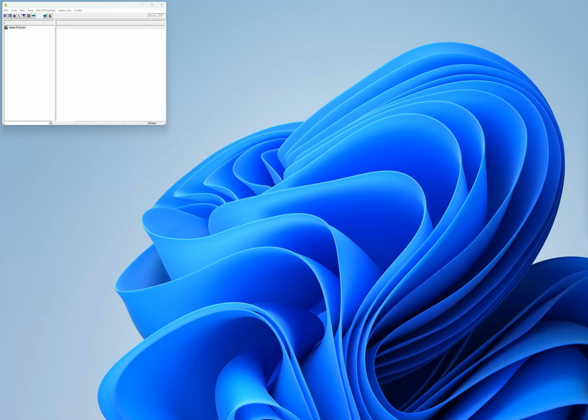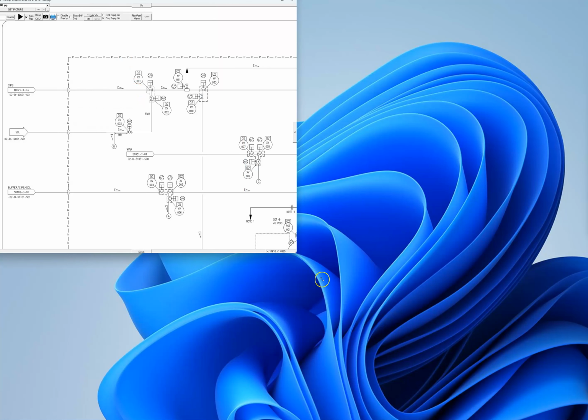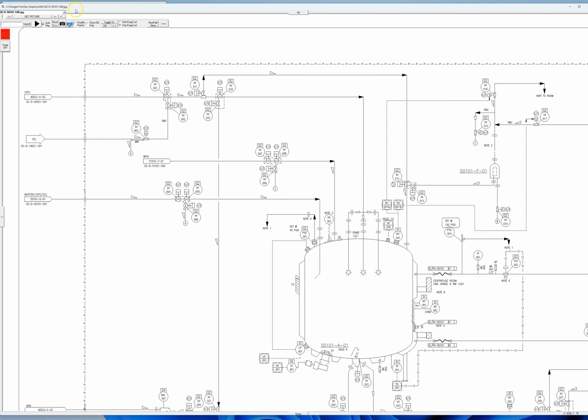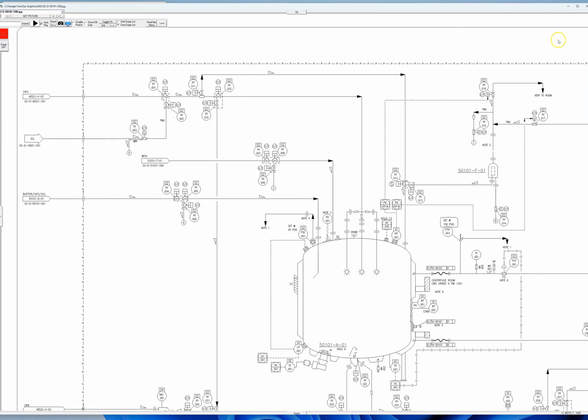Hi, this is going to be a video showing the new functionality of Triangle 5, and that is the digitization of the P&ID for flow path generation and Delta V integration. You can launch the tool, the new functionality, by going to Tools and CIV. When you do this, it pulls out the P&ID, which has been digitized. You then digitize it from there.